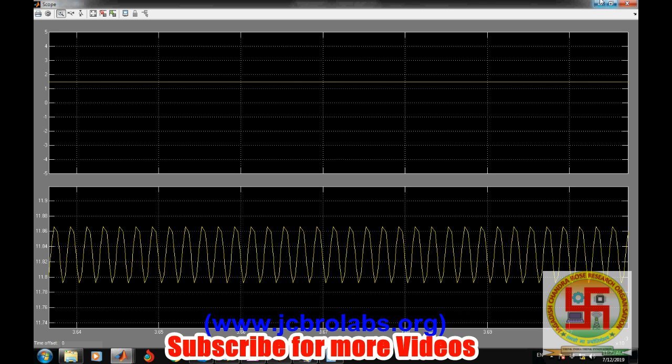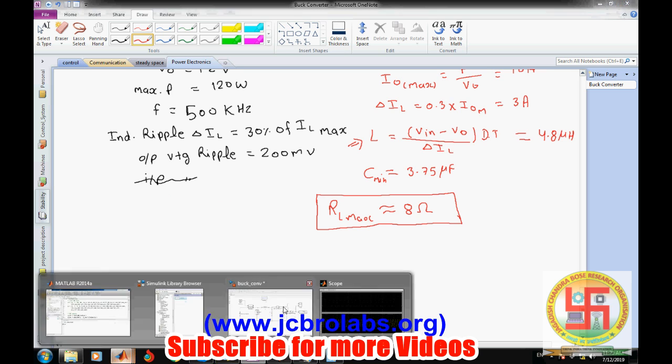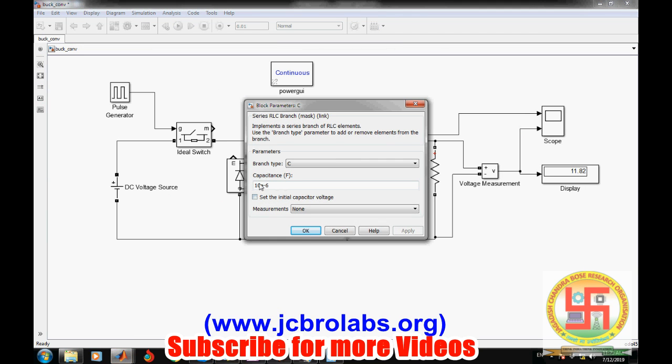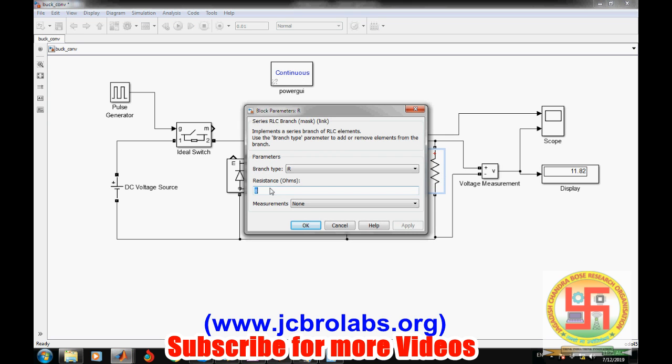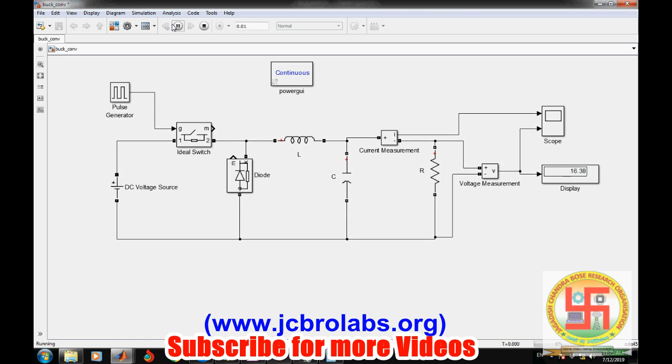Now let's change it back to the previous value, that was 3.75, and let's see what happens to the R, because that was the maximum allowable limit of the resistance. Let's say we increase the value of R to 20 ohm. Let's see what happens. Output will no longer hold the relation, and now we are not getting the exact 12 volt, we are now getting 16 volt.